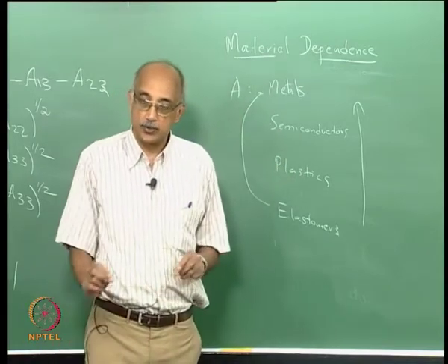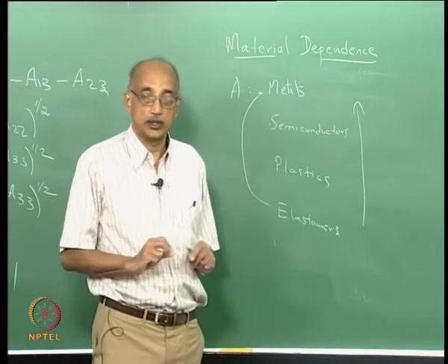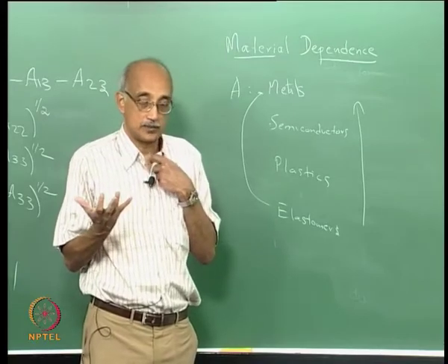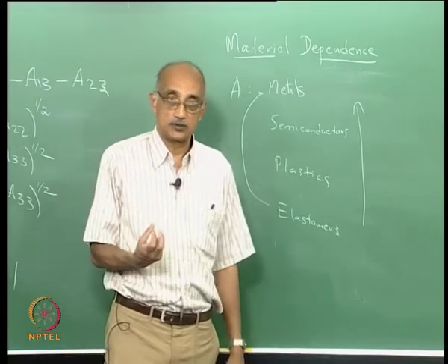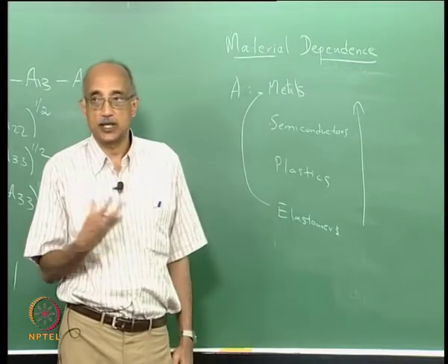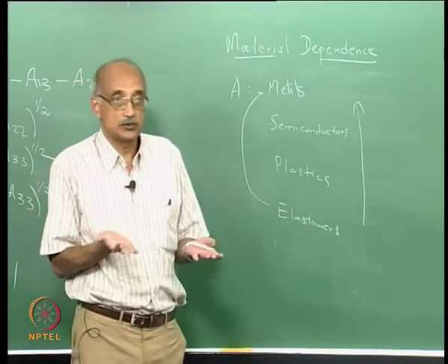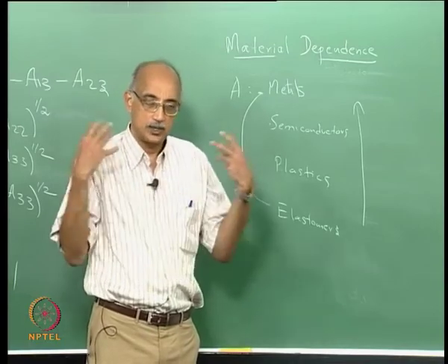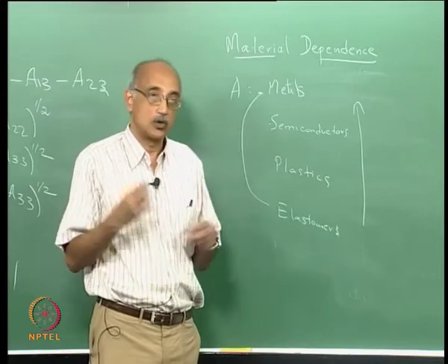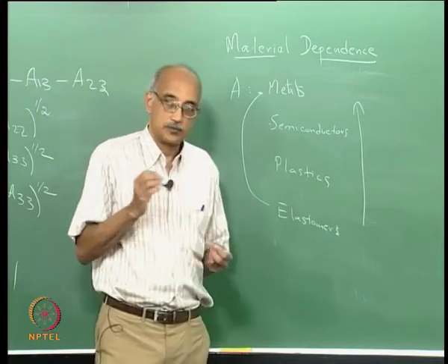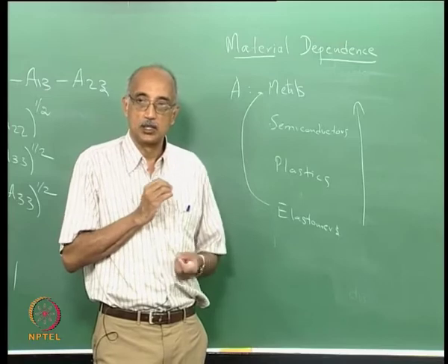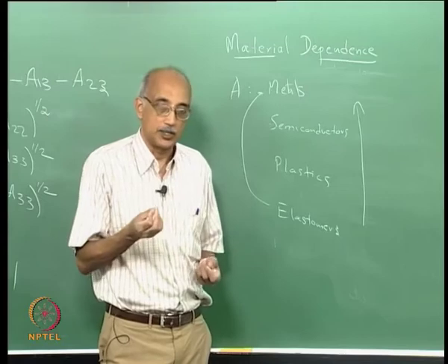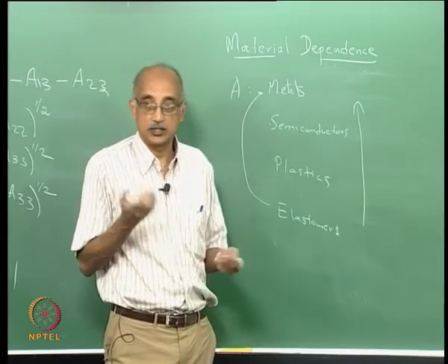That makes sense, but the problem is, from an electrical conductivity viewpoint, plastics are much worse. They are more likely to build up a static charge. So, electrostatic attraction forces will be much greater when you use plastics compared to when you use metals. So, the net adhesion force may actually be increased by using plastics instead of metals. So, you have to think about it in a systems way. You have to think about all the implications of the material pair that you are using on the associated adhesion forces and make the right choice for your application, whether you are trying to maximize the adhesion or minimize the adhesion.